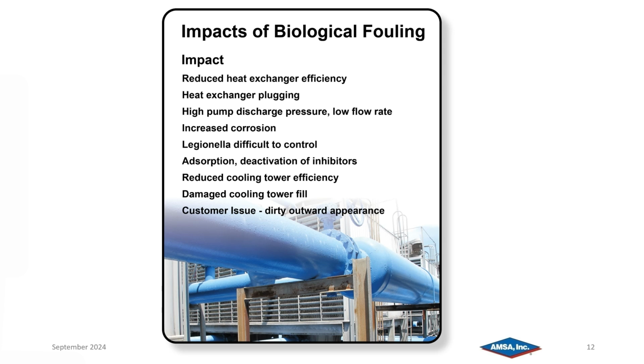Legionella is protected by biofilm deposits. When biofilm deposits are allowed to grow to a greater degree in a cooling water system, you have a greater chance of those deposits sloughing off and becoming aerated from the system. When these deposits, or this bacteria, are let into the air, it can cause people to become sick and in some cases to even die.